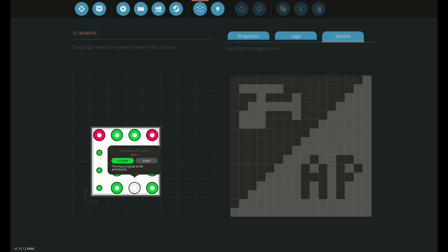Important note on the GPS, you have to make sure that it is on the outside of the craft. If it's boxed in, like in a compartment, it will not read, and so your craft will fly in a random direction. I assume towards 0, 0, because it's not getting anything from the GPS, but I haven't actually tested that, but that's what makes sense to me.